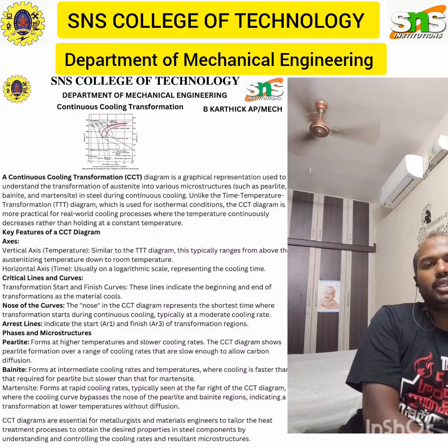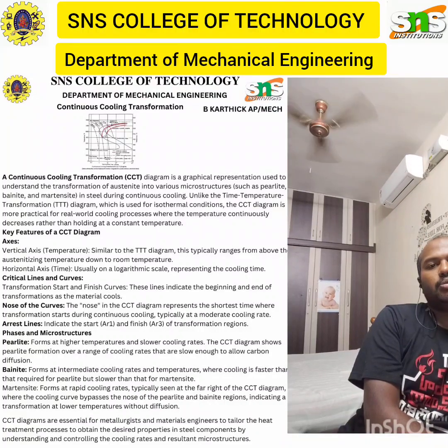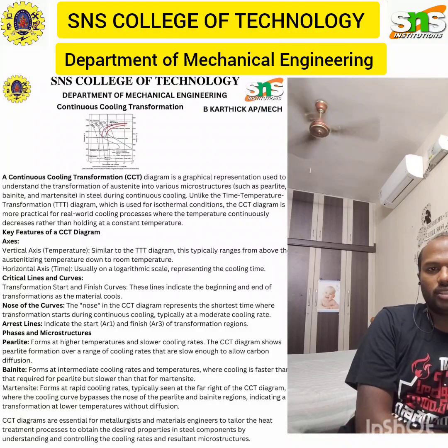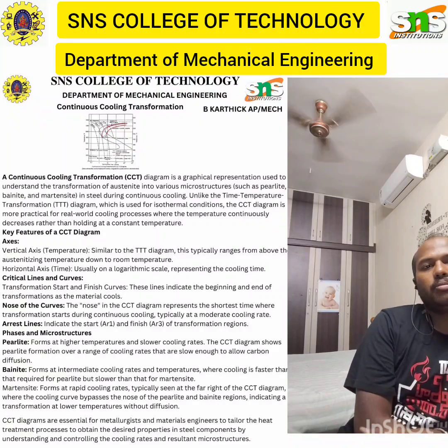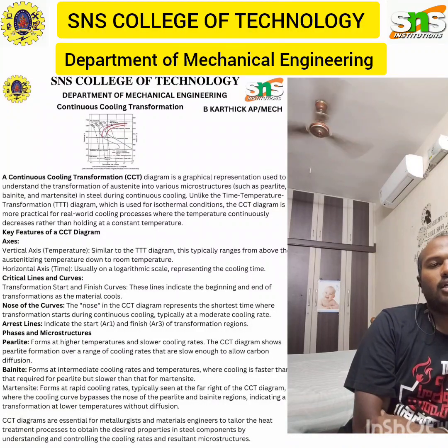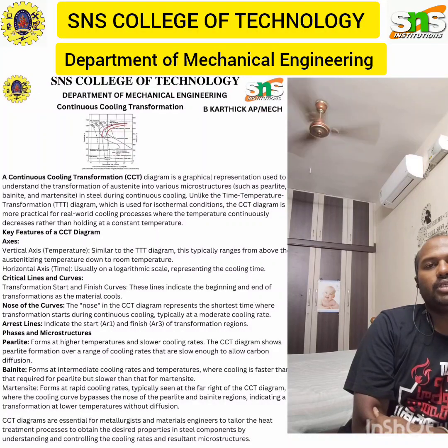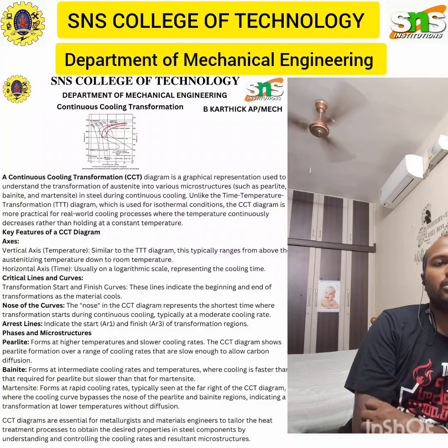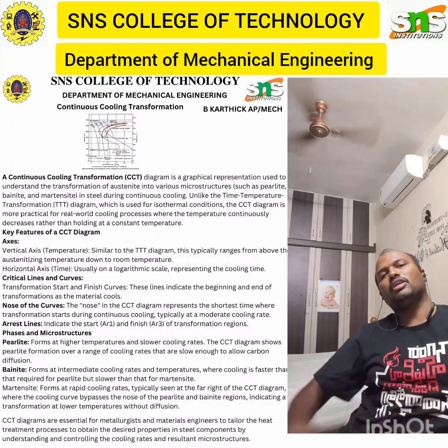In creating the diagram, we have some experimental procedures. First one is austenitizing, heating the steel to form a homogeneous austenite. Controlled cooling, cooling samples at various cooling rates and recording the transformation start and finish temperatures. The third one is microstructure analysis, analyzing the resulting microstructure using microscopy to determine the phases formed at the different cooling rates.